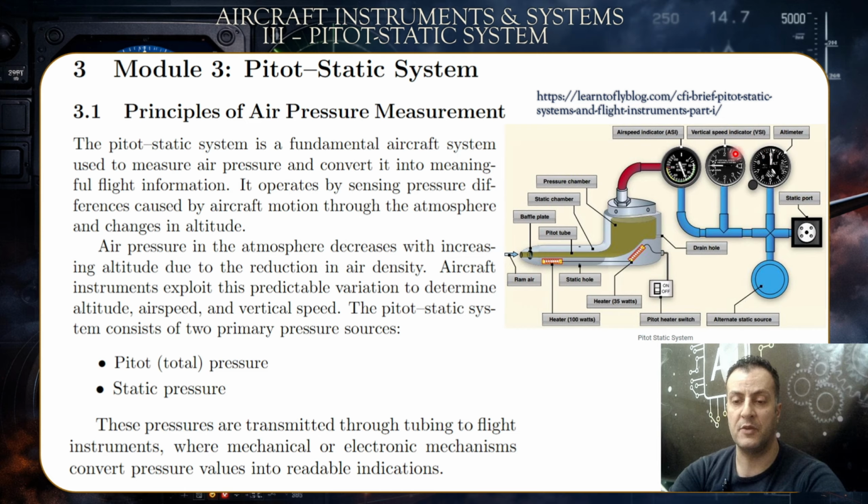Okay, the airspeed would be faulty, which has happened once on an aircraft, where one of the pitot tubes was blocked, which brought down the airplane. It crashed due to that factor. So now, speaking of which, how does the blockage of the pitot tube affect the airspeed indicator?